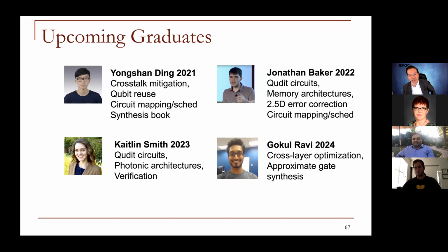But now we're interested in all kinds of things. We have techniques to try to mitigate phase accumulation errors, and techniques to mitigate amplitude errors. So we're interested in as much detail as you can give us, because then we can design specific transformations to our circuits that will help mitigate that noise on a per-qubit, per-coupler basis.